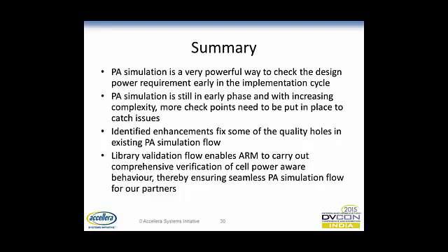So that is it. As we have seen, power-aware simulation is a very powerful way to check the design power requirements early in the implementation cycle, but power-aware simulation is still in an early phase, and with increasing complexity, more checkpoints need to be put in place. We discussed a few of the enhancements that fix some of the existing quality holes in the current power-aware simulation flow. With increasing flow requirements, the library modeling complexity is also increasing. So there is a necessity to have an advanced library validation flow as well to do comprehensive verification, thereby ensuring a seamless power-aware execution flow for our partners.